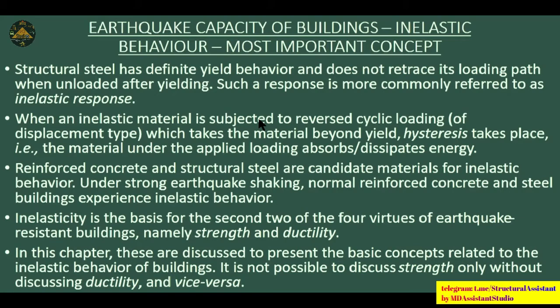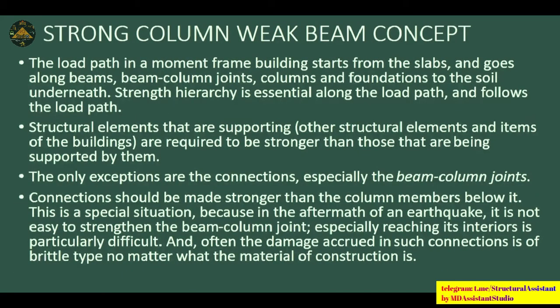When an inelastic material is subjected to reverse cyclic loading, for example if earthquake forces strike a beam and then, after the removal of earthquake forces, it tries to come back, hysteresis takes place in that case, and the material under applied loading absorbs or dissipates energy. Reinforced concrete and structural steel are candidate materials for inelastic behavior. Inelastic behavior is basically the basis for the second two of the four virtues of an earthquake resistant building, that is strength and ductility.